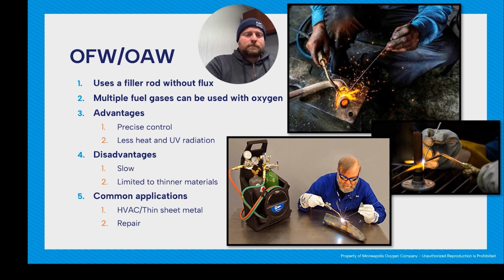Some disadvantages: it's very slow. It's limited to thinner materials. You're not going to be able to do really, really thick stuff with it. Some common applications, like I said, were HVAC or fusing thin sheet metal, and a lot of repair. If you're doing things like cast iron repair or things where you really need to control your heat input, this is a good process for that.